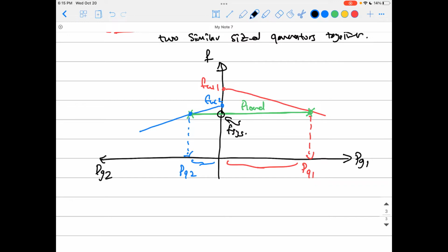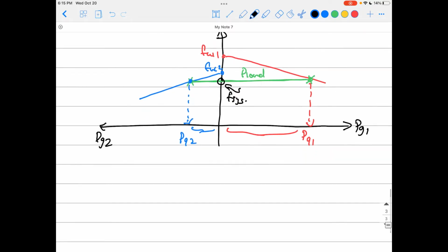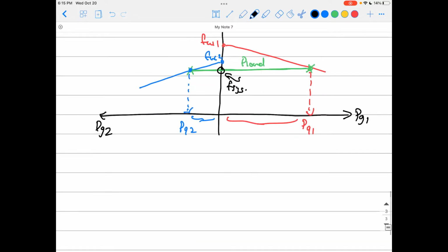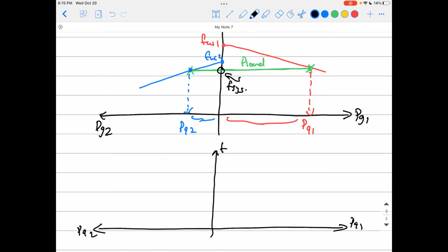so that's it. What's in your hand to do is controlling using the governor, and the governor will just change the FP relationship of each of the two generators up and down. It's up to you. And what will happen if you just move one of them up or down? Okay, so let me have an example here just to show you what's happening. So I'm going to plot this again down here. That is P generator 1, P generator 2, and that is the frequency. What happens if I just use the governor of generator 1 to reduce the no load frequency?